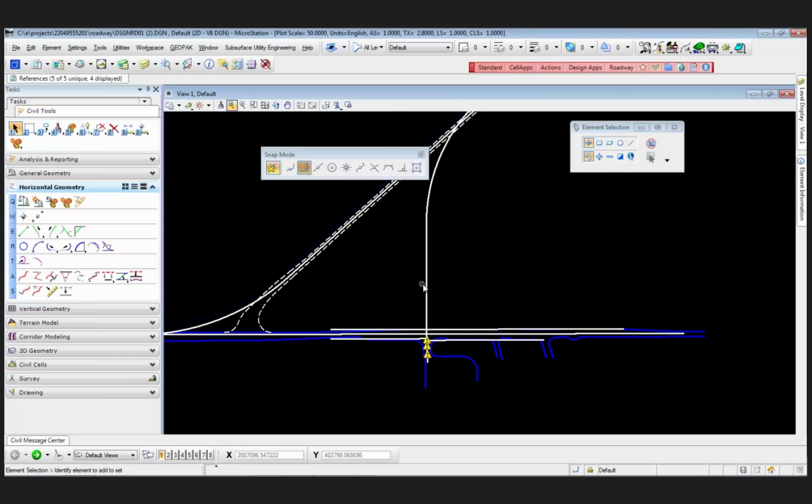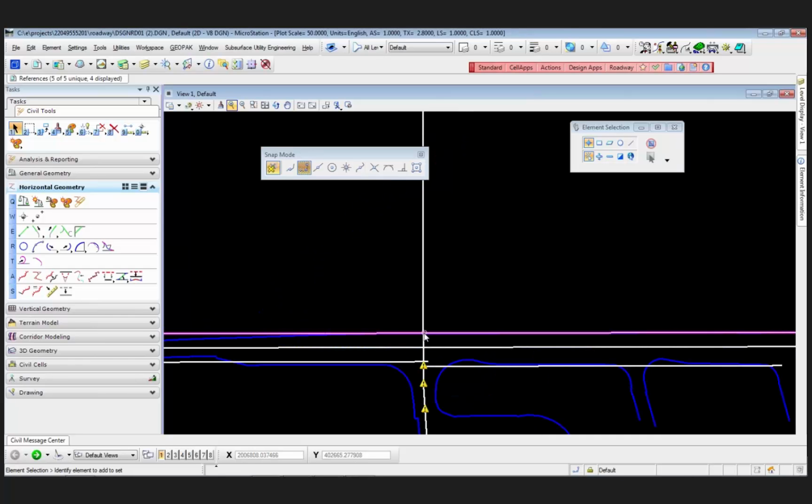But we also have, for example on this tool, I want to put in 4-lane divided planimetrics. And I want to do it within limits. Now I could use that same partial offset tool and do it however many times for the parallel lines, or I could just essentially set the limits for the lines and then do it once with a civil cell.